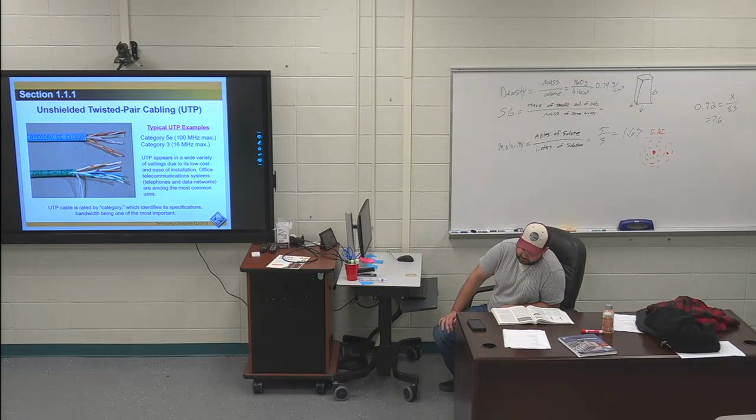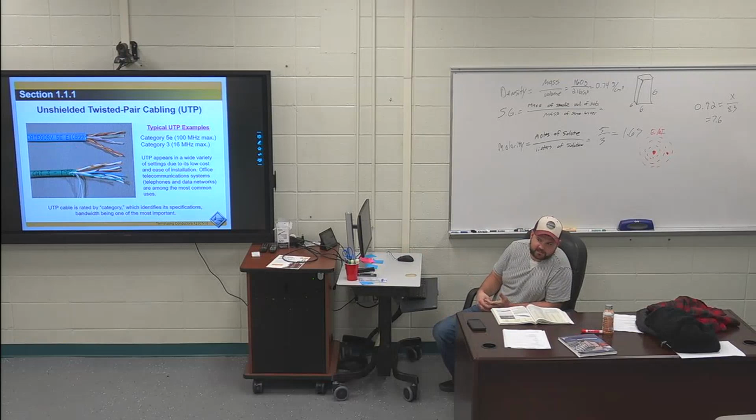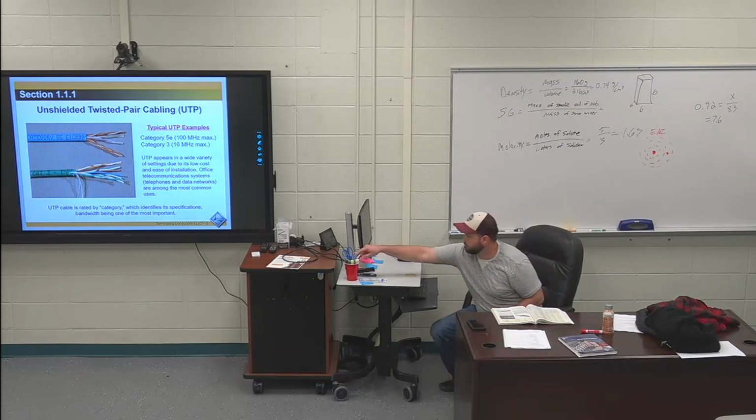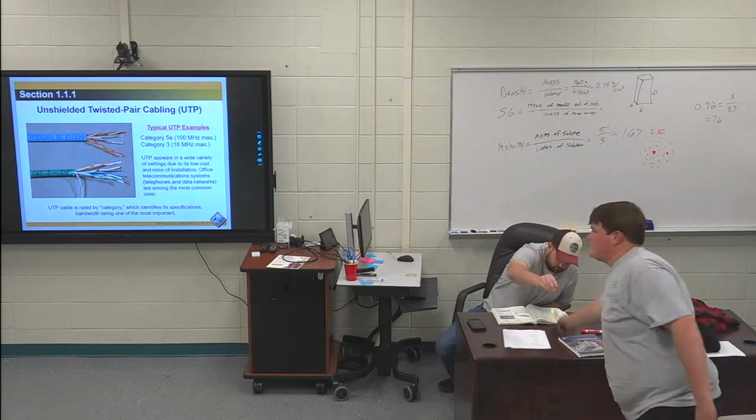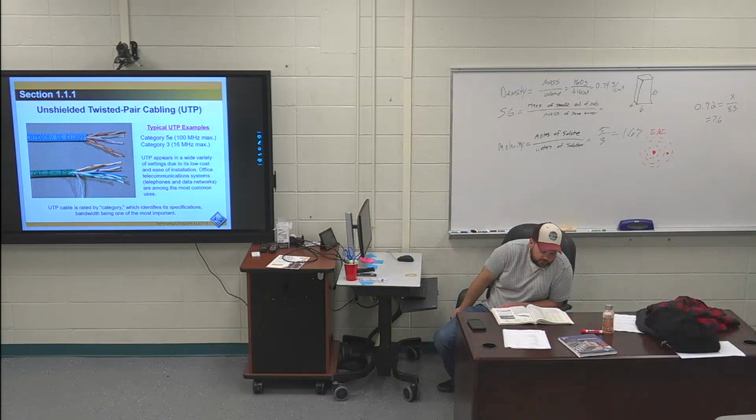113, under carpet telecommunication cable, UTC. Flipping over to page 4. So that last sentence before 114 is highlighted on page 4 as an online test question. So make sure y'all mark this as an online test question. When installing under carpet cabling, high traffic areas, heavy furniture locations, and under carpet power cables must be avoided.